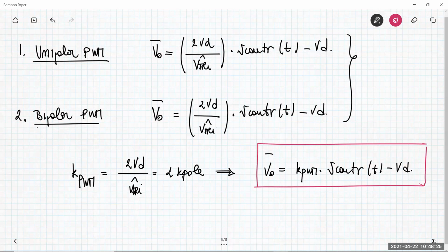So again, for the four-quadrant converter, we get an amplifier expression, in which the control voltage is the input signal that is amplified by the four-quadrant converter, and the gain is KPWM. That, by the way, is the 2 times that you can find for the two-quadrant converter. And then we have also an offset, a constant voltage that translates rigidly the characteristic.